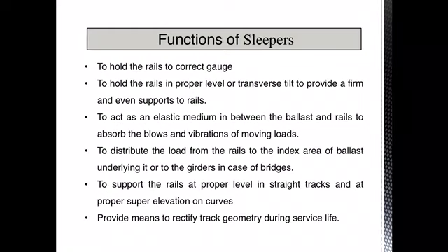The sleepers must also effectively distribute the loads from the rail section to the wider area of the ballast underlying it, in the case of normal railway tracks. And if the rail track is on a bridge, the sleepers provided must effectively transfer the loads from the rails onto the girders. Also, they should provide a proper level on the straight track, and proper super elevation has to be maintained on the curves.